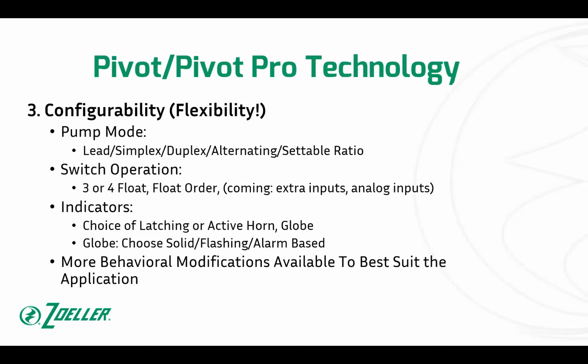Now that's fine. And sometimes people would use a smaller pump for the lead pump because it was a dewatering situation, and the 100-year rain pump is the bigger pump and it's in lag and you don't want to run that one. But the inherent problem with a lead lag selector switch, as the option used to be called, is that the lag pump never runs. It sits there dormant unless somebody's getting in there to purposely turn it on. So we decided to fix that problem.